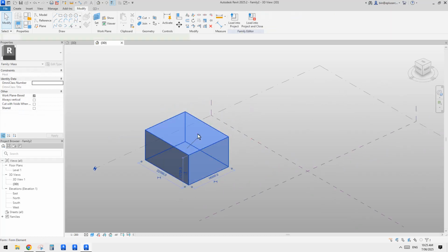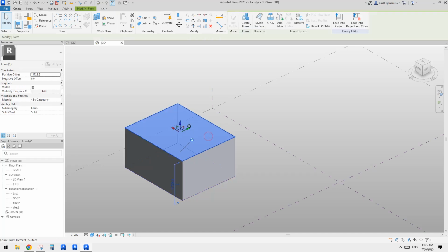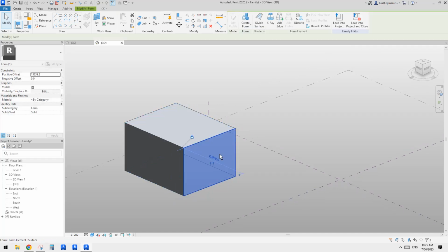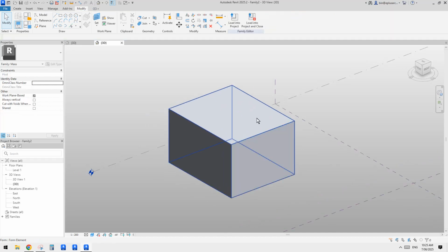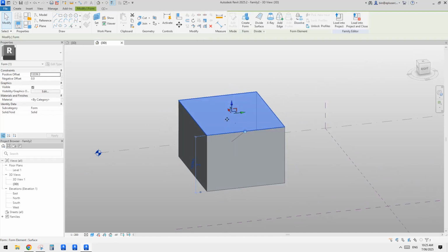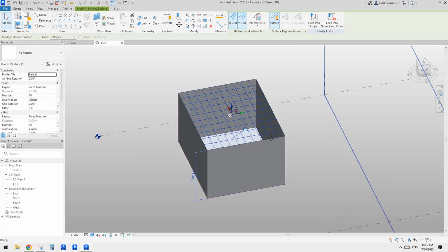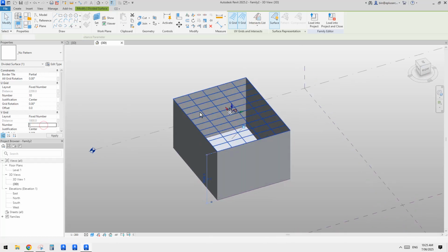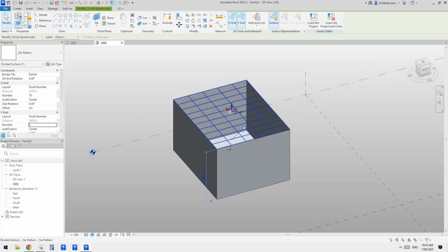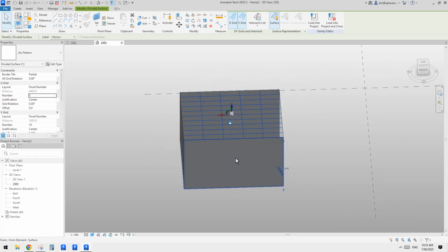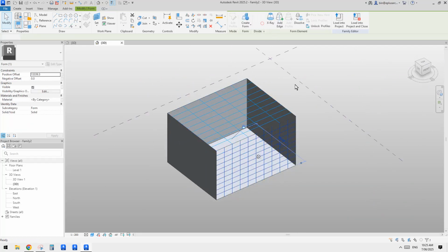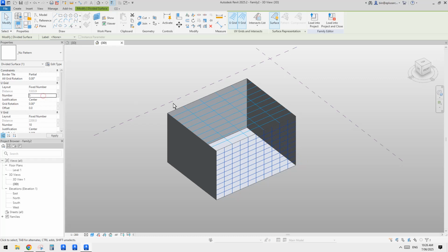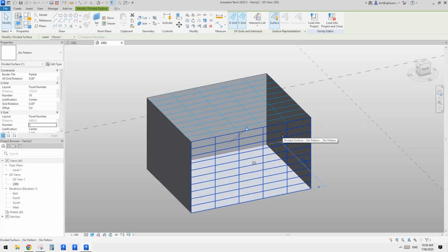So now we can use this surface, for example, as a horizontal example. Use this for a vertical example. So let's do it. Tab, select this until you find this surface, and do divided surface. And then I'm going to just reduce the number in one direction. So maybe the other way. How about this? Okay, and then we can just do this one. Tab, select this surface, divided surface, and try, I'm not sure which one, 5? No, wrong one, sorry. 5. Okay, so now we have this.